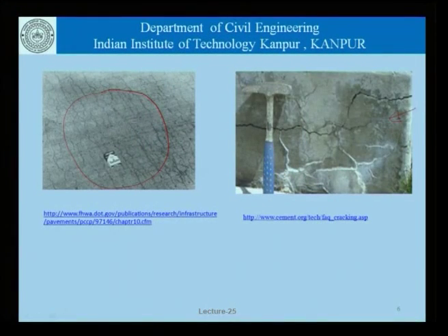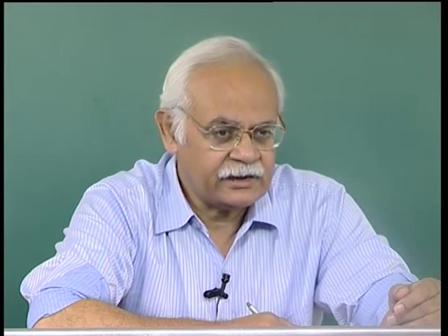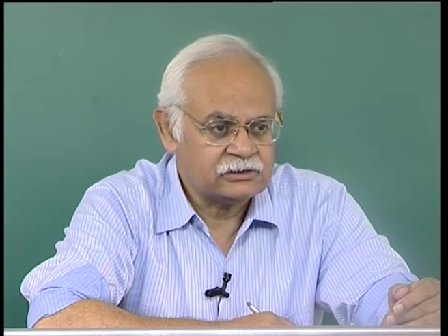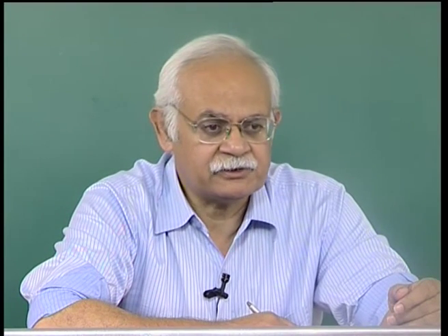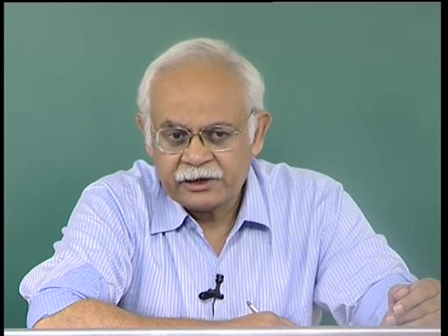This picture here is a slightly different representation of what happens when alkali aggregate reaction occurs. We can see here that this crack here is a fairly wide crack. So, alkali aggregate reaction induced cracking in structures is not insignificant. It is not something which we would like to ignore, because such cracks have structural implications, they have durability implications, and so on.